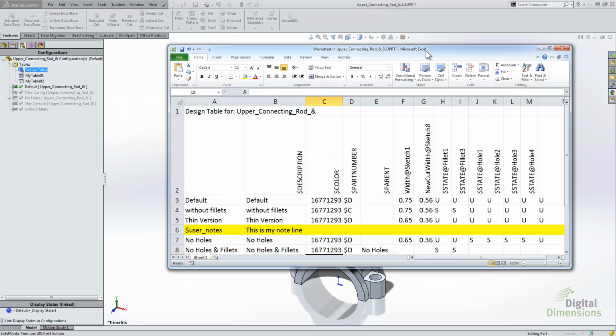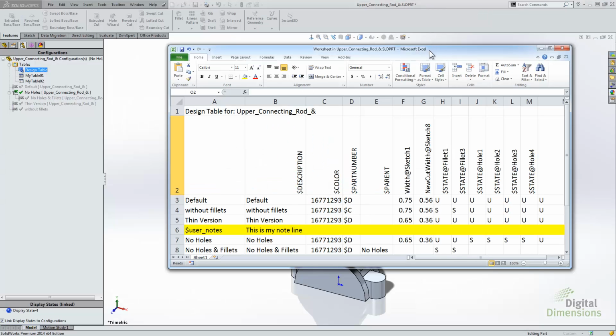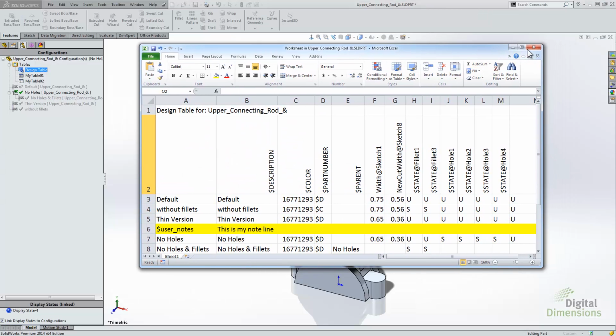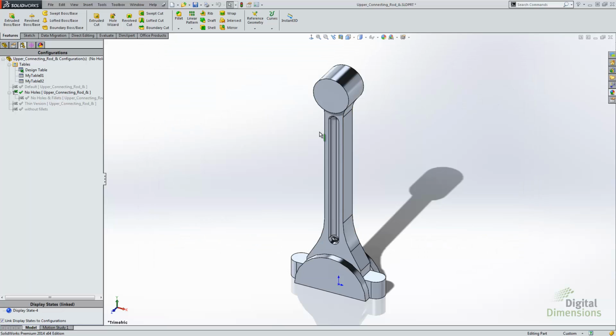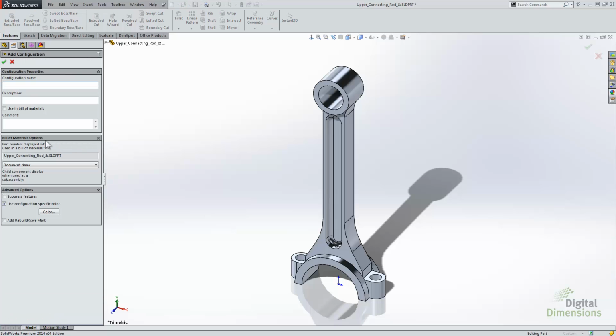Okay. All right, so I'm going to close out of my Excel program. Thing to keep in mind is that you don't need to actually save the table because it's an OLE object, linking and embedding. It automatically writes back to the part file, so it is an Excel file within the table. So all the stuff is actually still being controlled, this time being a little bit higher level there.